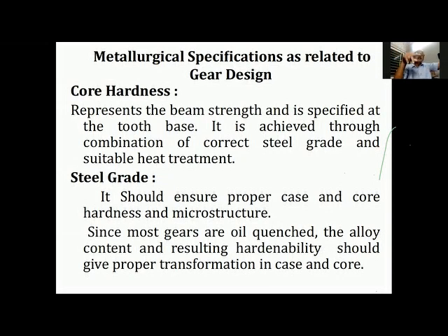The first peak of the first curve is in the region of 35 to 36 HRC, which represents a predominantly martensitic structure, whereas the other peak of the fatigue curve is in the region of 42 to 43 HRC, and that represents predominantly bainitic structure. Okay.